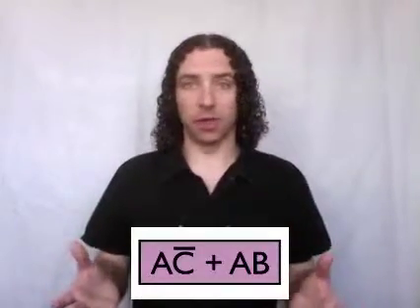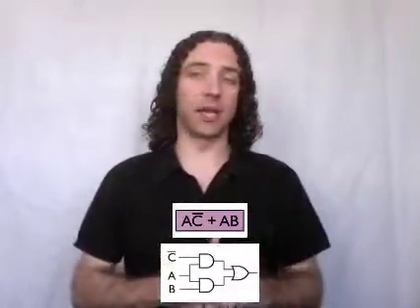So now that we've got this basic relationship that describes A C bar plus AB, we know from there we can change this into a sequence of logic gates and put them together like this. Note as well, I'm not going to worry about it too much in this case, but you could also refactor it differently so it was A and C bar or B, and that would give you a system like this. They're both equivalent, it's just going to be different layouts of how things are connected. So now that we've got this combinational logic, this simple connection of logic gates that actually will answer the question of whether or not to go outside, we can use this as an example for other discussions.